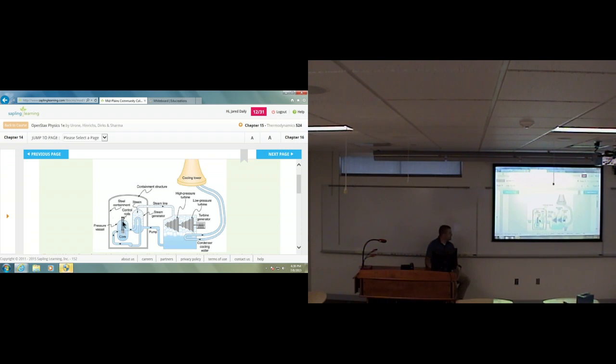And as it heats up this water, it gets up to 300 degrees, this water goes into another water container where it turns the water into steam. The steam leaves the reactor. Notice that you don't have any lines that are connected directly from nuclear reactor to the outside. These are completely sealed so that they never come in contact with each other. They come in thermal contact, but they don't exchange any kind of materials with each other. So that the steam out here is low radiation instead of high radiation. This stuff is high radiation.